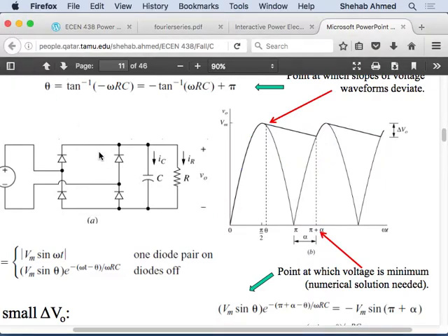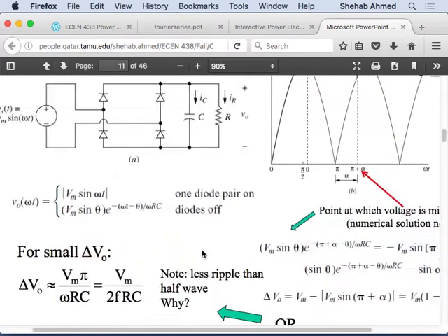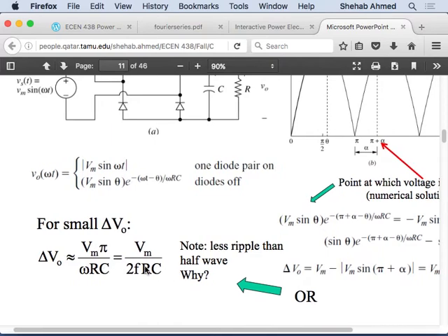In the homework, you saw something where they would tell you the circuit has a time constant equal to twice the fundamental period or something, right? Or it has a low time constant, no? There was one where you compare them. Yeah, they give you two time constants for the circuit, right? So it's similar to that. If your RC time constant is large enough, it means that you will discharge slowly, and hence you will not need to use the exact solution. There is an approximate solution that was derived in the textbook that you can use directly.